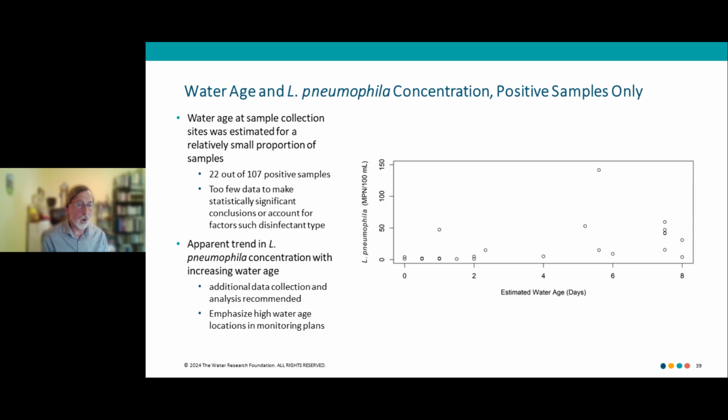We didn't have water age estimates for many of the data. In fact, only 22 out of 107 positive samples had water age data associated with them. There is an apparent trend in Legionella pneumophila concentration with increasing water age, but we have to take this with a grain of salt. Too few data, and it makes sense that there would be a trend with increasing water age, but it's going to be correlated with a lot of other things.